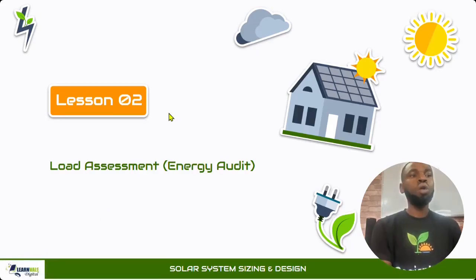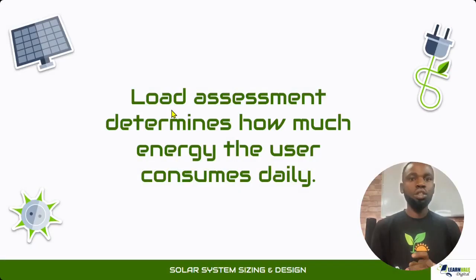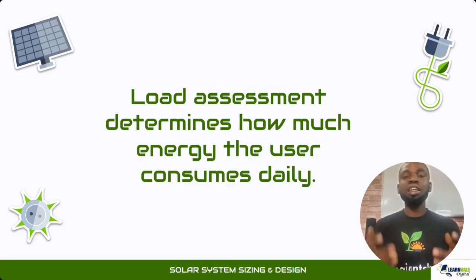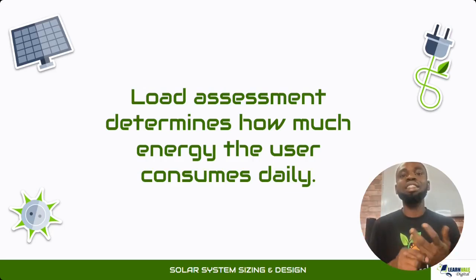Load assessment is all about ascertaining the amount of energy a user uses on a daily basis. How much energy does the client use on a daily basis? That is what the load assessment helps you ascertain, and that is one of the most important pieces of information or data you need to conduct a system sizing for a client or at a site.